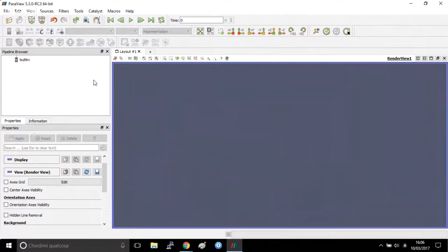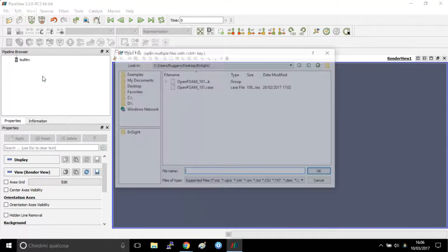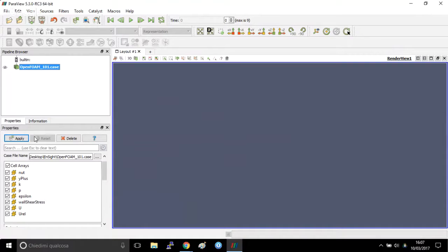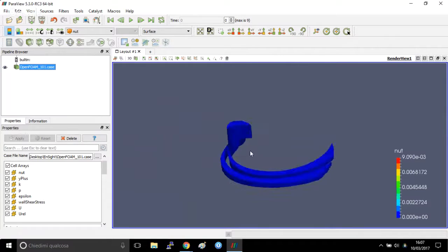Hello everyone, we're going to discover today how we can calculate aerodynamic forces and torques out of the results of a CFD simulation performed with SimScale. Obviously, the first thing we have to do is open the .case file. We download it from the platform, and in order to open that, we use ParaView, which is an open source software available for everyone to download.